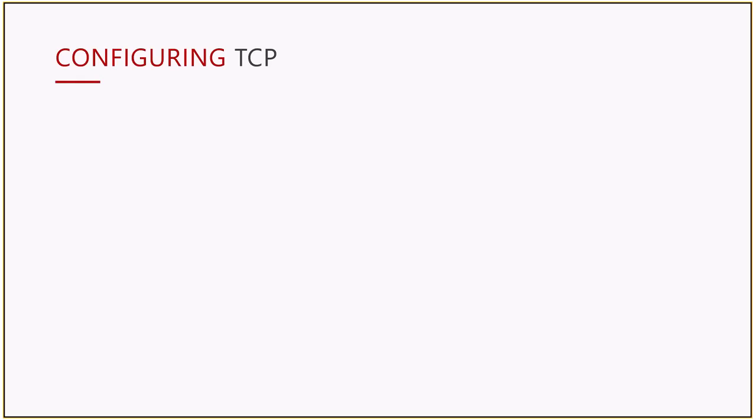Configuring our TCP. The robot needs to know the position of the TCP relative to the flange, and to be able to pick up things and place them in other locations that you want to. This is done by entering the 3 position coordinates.